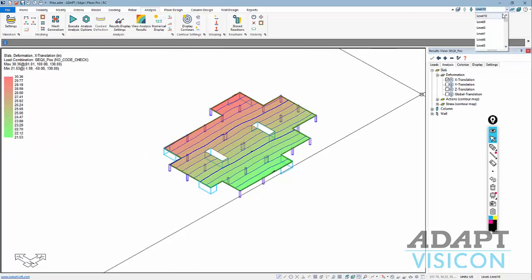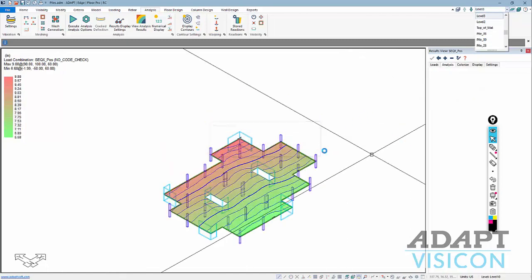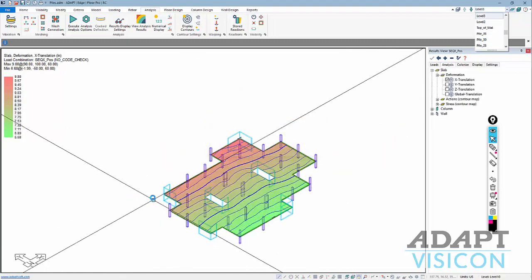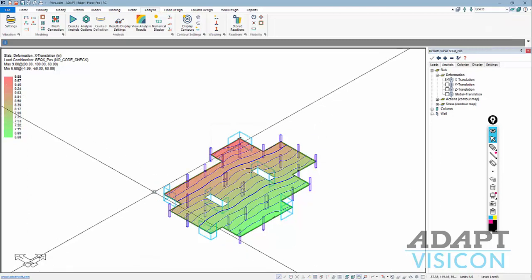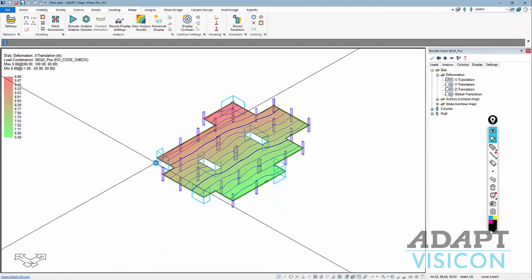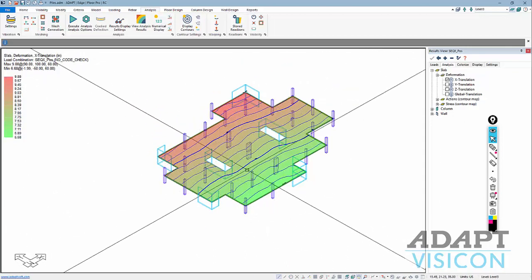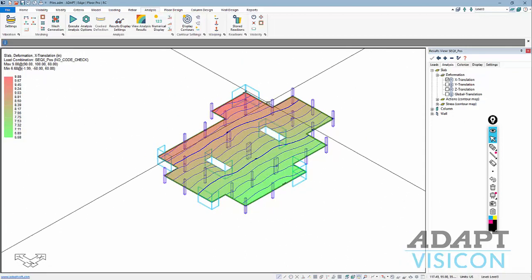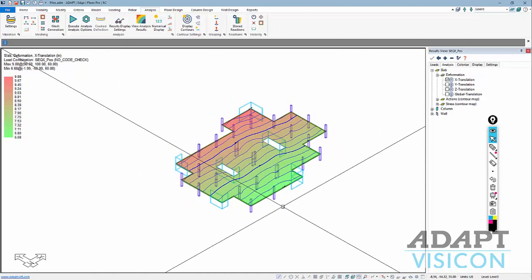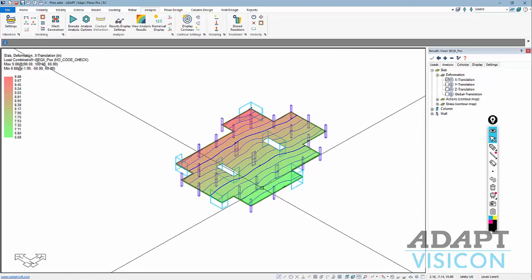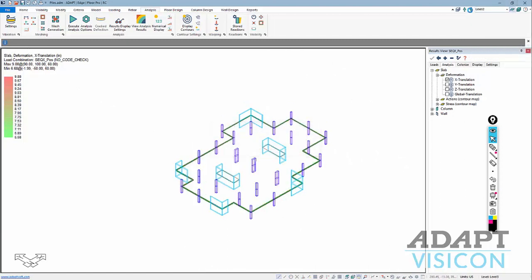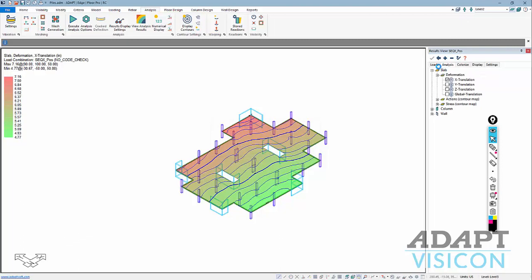If I navigate down into the building, we can see additional locations of displacement. So this obviously was not sized for proper spring stiffness interaction with the soil superstructure, and the seismic loading was arbitrary, so we had a fairly high base shear for the loads applied to the structure. If we go down to the lower levels, let me get down into the piles. We may want to see the reactions of the piles.